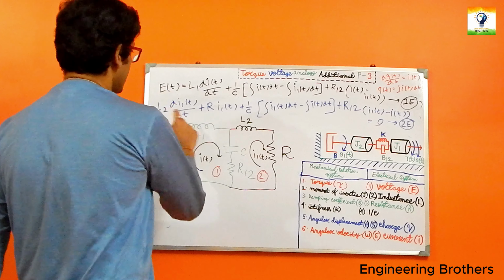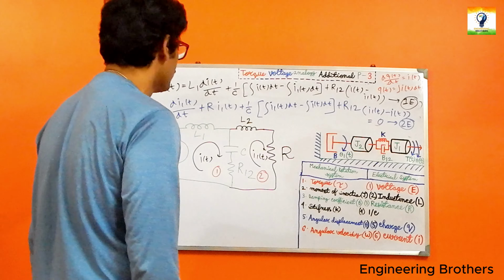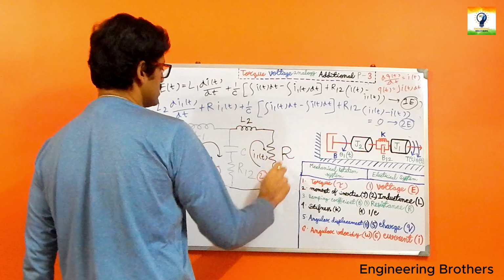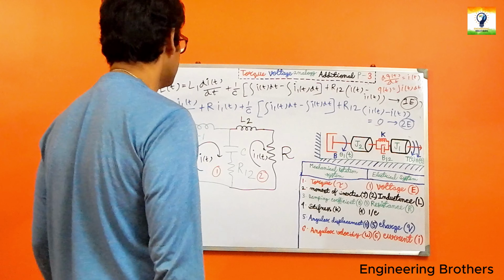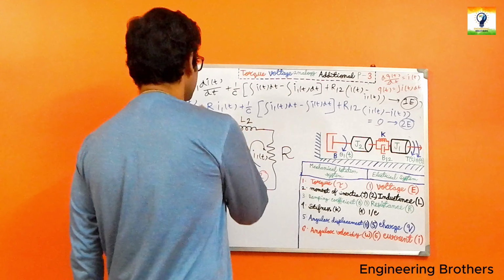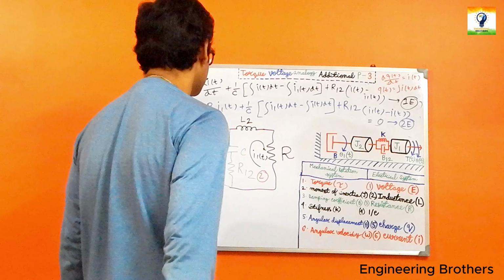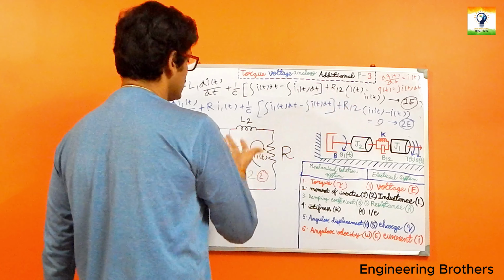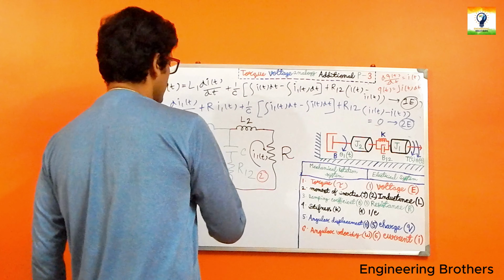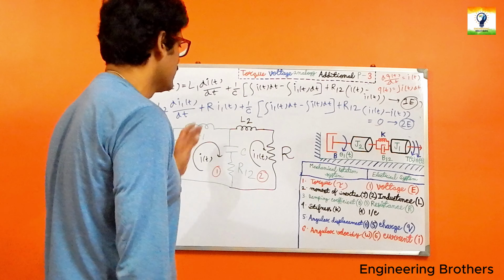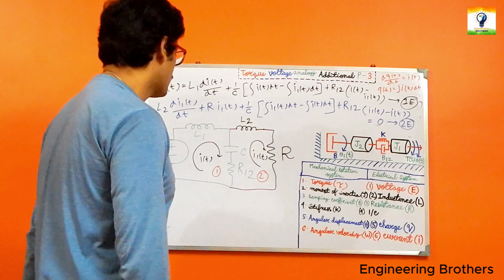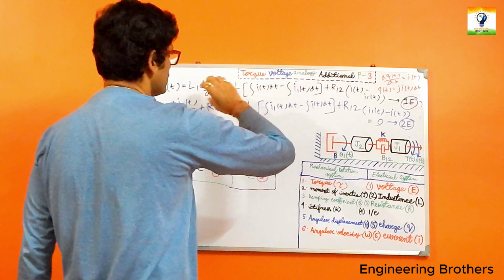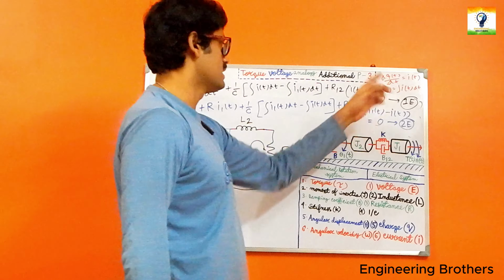We have got the inductance L2 present over there, because we do know that the voltage drop across the inductor will be L2 d/dt of I1T, because in this loop 2 the current is quite naturally our I1T. Similarly, for our resistor part also, the voltage drop across the resistor will be R I1T, and the capacitor and the R12 are placed in between our two current elements of I1T and IT over there, and we have already included that over here. Now, quite naturally, if you apply the KVL at the loop 1, we have got the first electrical equation, which we have considered as our 1E.